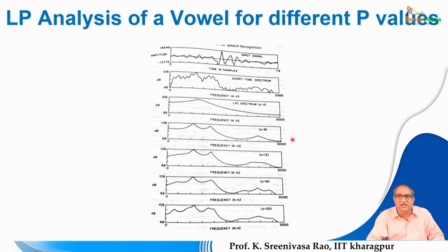Whereas in the error analysis, what we observed is that as you increase the linear prediction order, the error is reduced, and the error is drastically reduced up to orders like 6, 7 and 8. Afterwards the decrease in error is less. Therefore, the reasonable order for performing linear prediction analysis for vowel segments is around 8 to 12, like 10, which is a decent via media.